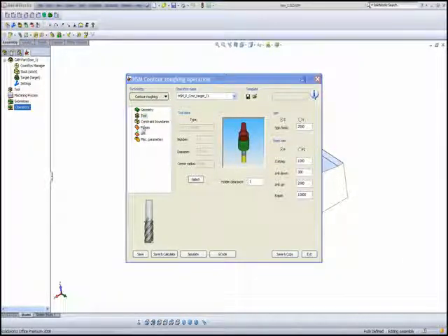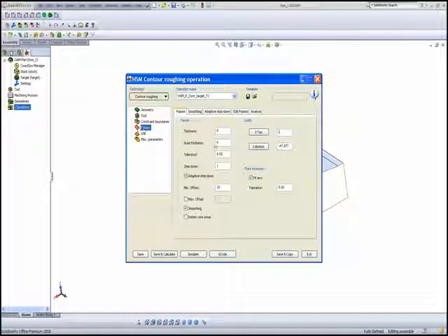Let's go now to our passes. In our passes, we will leave a thickness offset to the tool of 0.5. You'll note that when I put the value of 0.5 here and I go to the next field, the 0.5 is automatically added to my axial thickness, to the bottom of the tool.